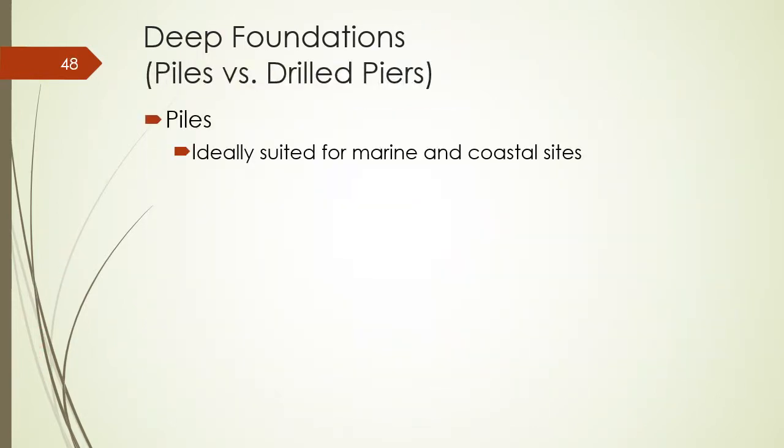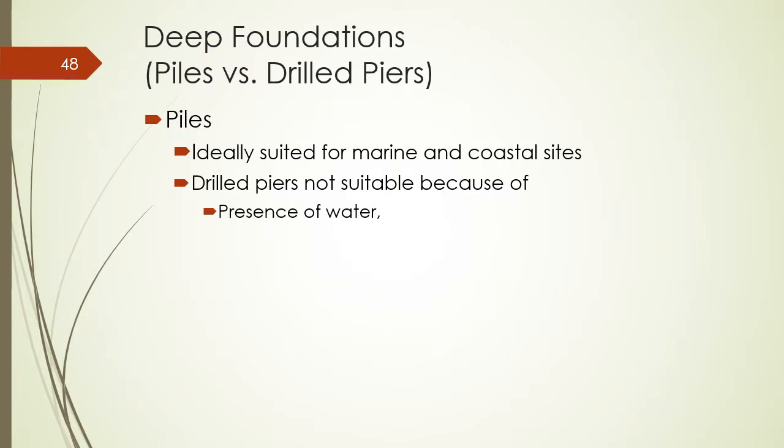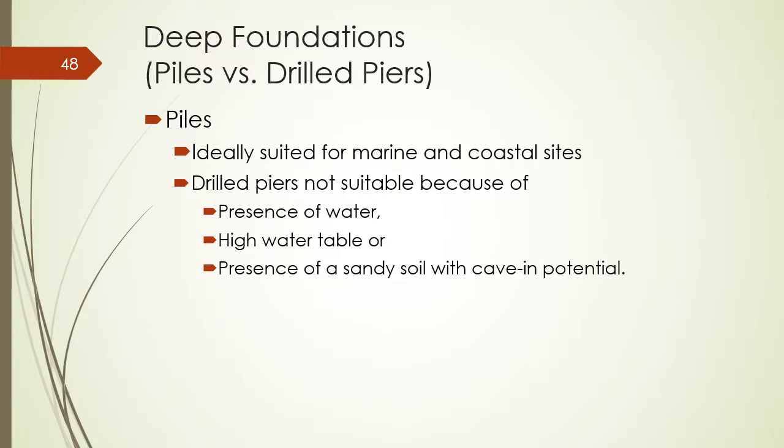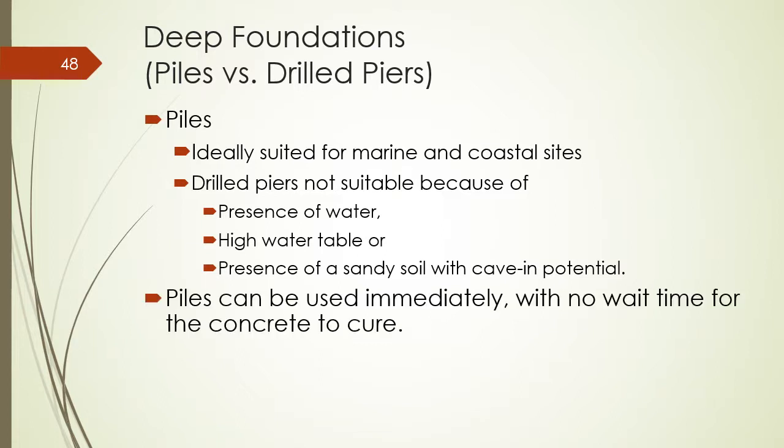So piles can be suited for marine and coastal sites. Drilled piers would not be suitable because there is water present, there might be a high water table, or we have sandy soil with a cave-in potential. The advantage of piles is that they can be used immediately. We do not have to wait for the concrete to cure.